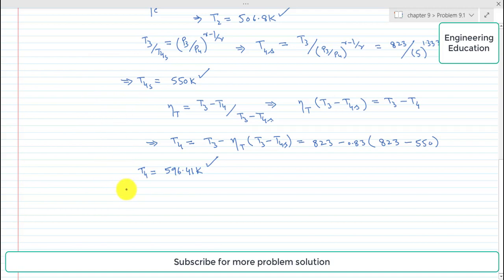First, the work output from the turbine, which is represented by Wt, is equal to Cp into (T3 minus T4). So Cp is 1.15 kilojoule per kilogram per Kelvin for the expansion side, T3 is 823 and T4 is 596.41.